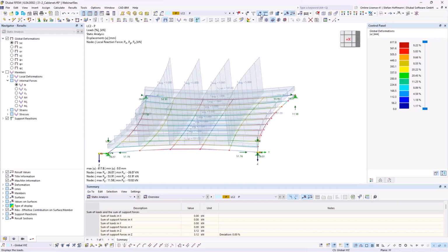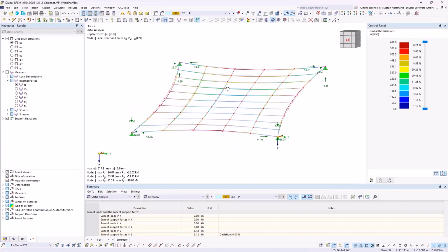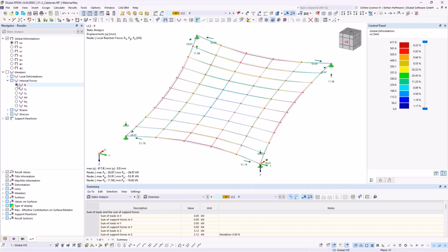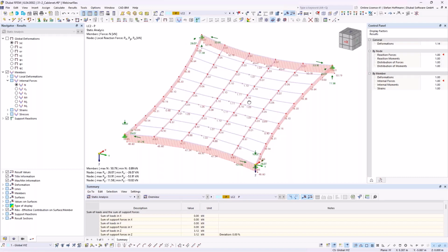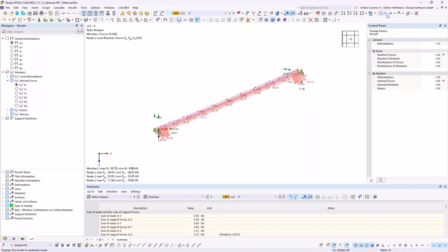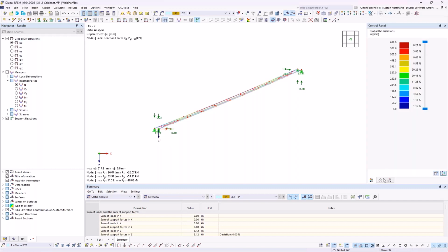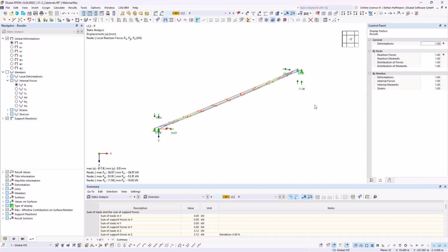So you can see we now have, with the 5 kilonewton meter in this direction, such a shape where we can quickly investigate the normal force distribution. So we most likely reach 5 kilonewton in this direction and 1 in this, and all the others are identified by the geometric boundary. So if we would like now to observe the deformation, we can check it like this, and the best thing is to scale it for 1.